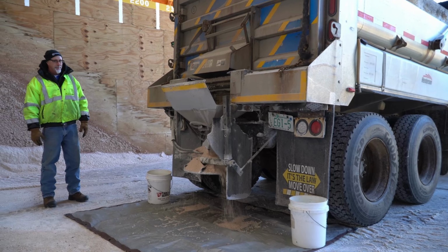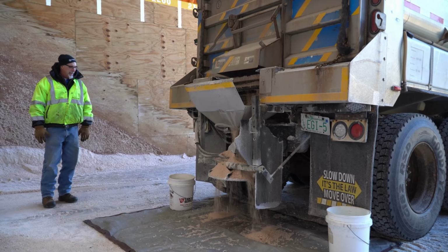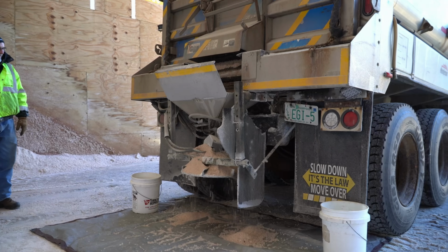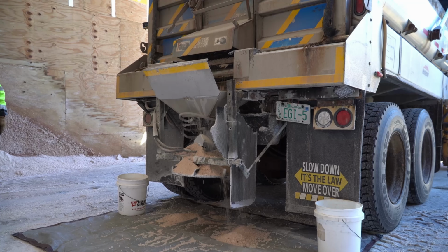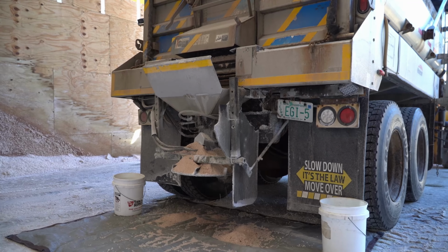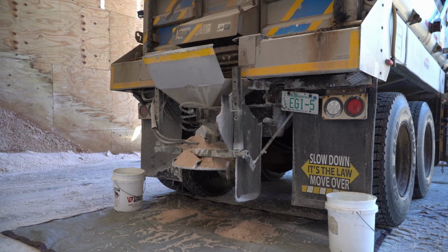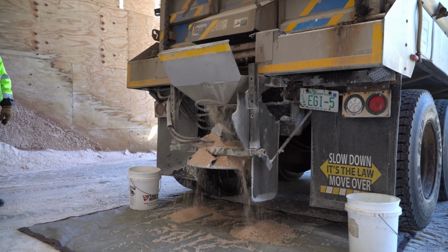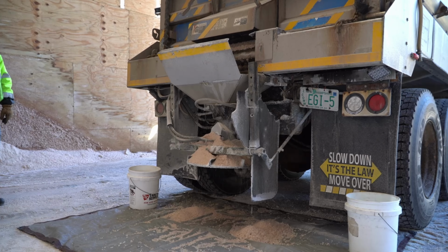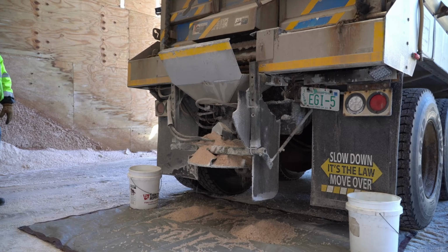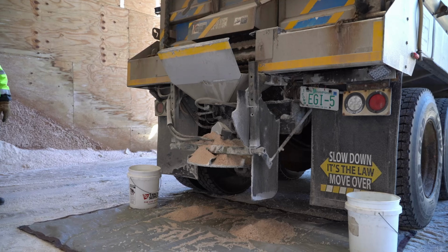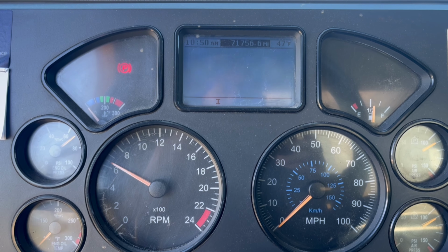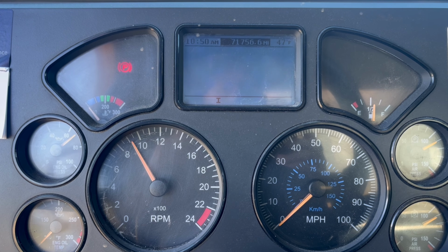We'll first measure output using a stationary check. This verifies that the spreader can physically produce the expected discharge rate under controlled conditions. Material is collected over a timed period, typically 30 seconds, and converted to pounds per minute. For computerized systems, we compare what the system is set to apply versus what it actually produces. For consistency, our check uses a 20 mile per hour reference speed. At 20 miles per hour, each pounds per lane mile preset corresponds to an expected pounds per minute discharge rate.